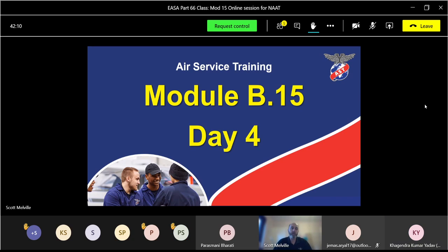Normally, if the pressure builds up, it will push the diaphragm up, looking at the diagram, to open the spill valve. But what if there's a hole in that diaphragm and there's nothing to react against? So what could happen now? Is it hunting? Yeah, you'll get hunting. And what causes that?